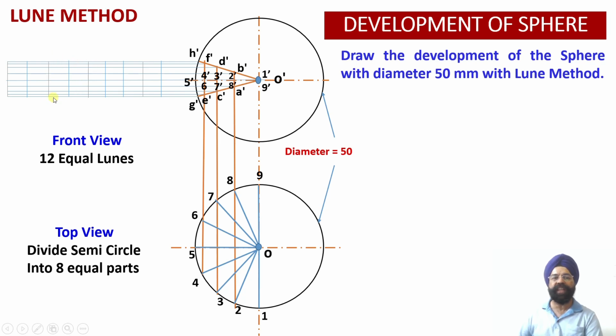The distance between the vertical lines would be, please check, the chord length, not the arc length. Ideally it should be arc length, but in manual drafting we are not able to measure arc length over there. If you are using the computer or making an industrial drawing using some software, obviously you can measure this arc length properly, and once you measure the arc length, the distance between the 2 points on the arc has to be drawn.